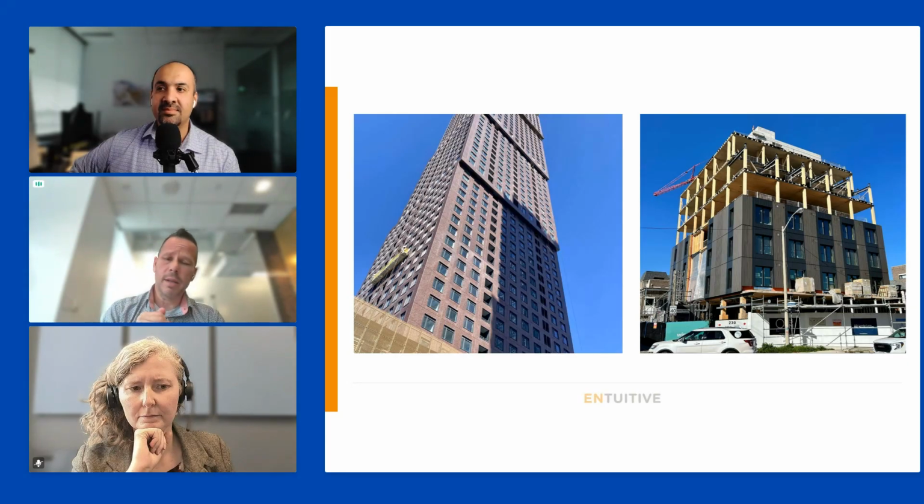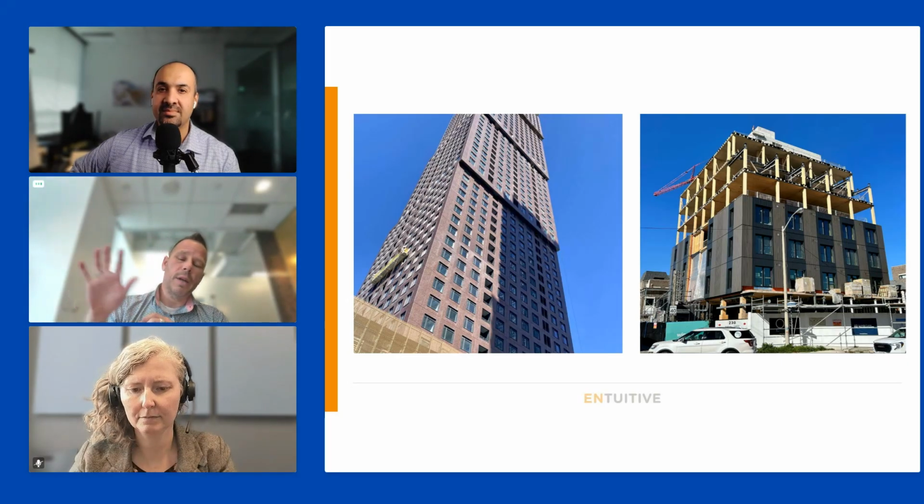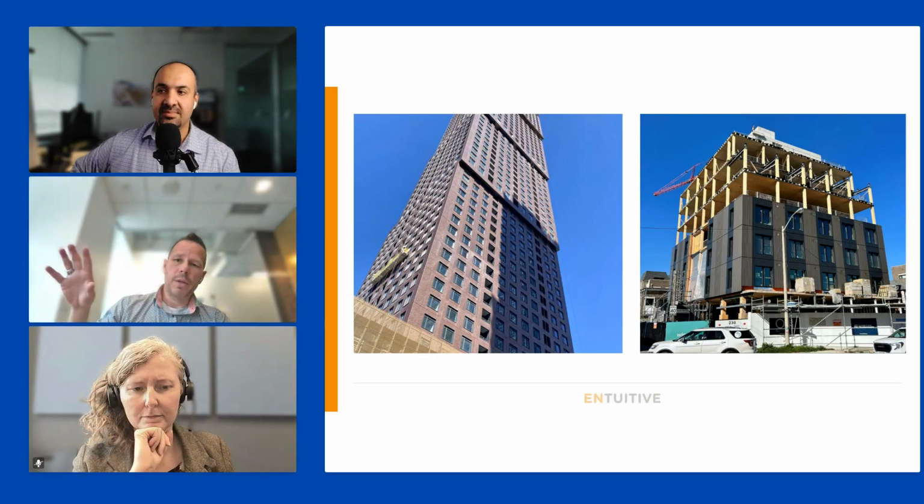The other project on the left was a project that I worked on up in Vaughan. It's a high-rise building. This is precast cladding. I have another example in a couple of slides where this panel is on a trailer. So this is a large precast unit. It has the window pre-installed in the factory, and then it's hoisted up on the building. And then the sealants are installed between the panels, and the building is essentially air water tight fairly quickly.